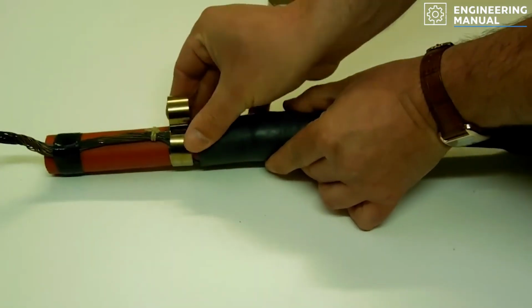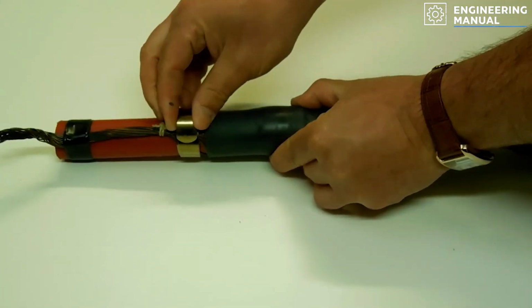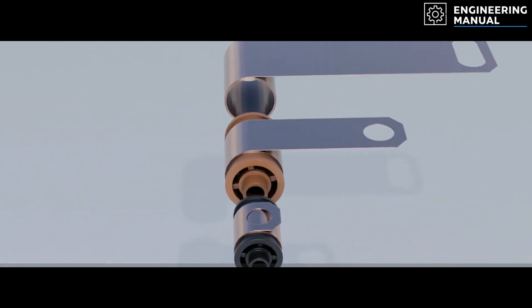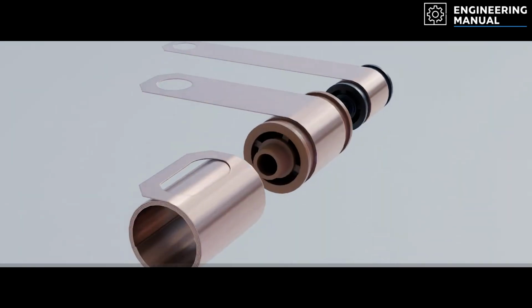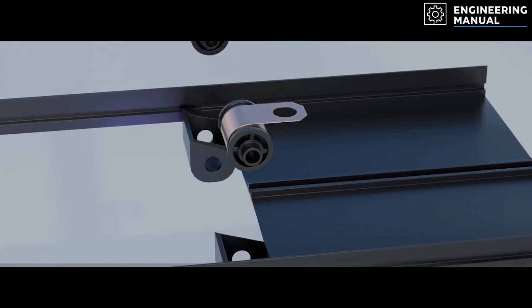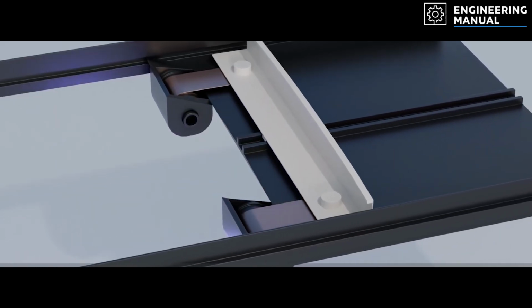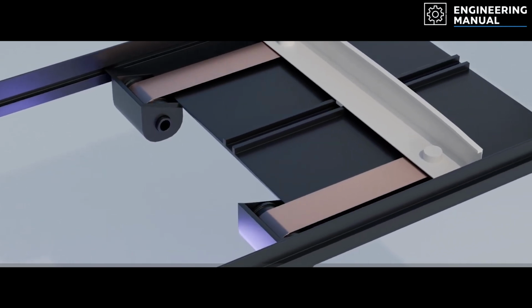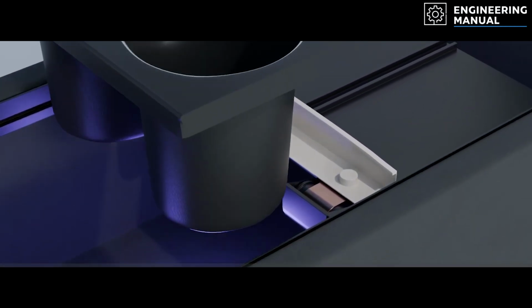The governing constraint is material fatigue under repeated bending along a single radius. Unlike helical springs, stress is concentrated along a narrow band that experiences cyclic flexure with minimal redistribution. Another limitation is storage geometry. The spring must be wound tightly in a housing, which introduces contact friction between layers. That friction contributes to hysteresis and can destabilize force output in precision systems.